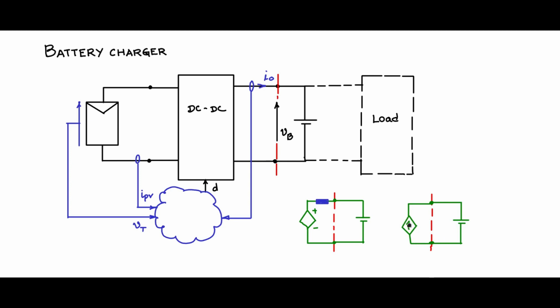It has the necessary impedance inbuilt within it, so that there will always be a current limit. Current sources and voltage sources can be connected in parallel. So we will follow this model, and that is what we will introduce into this control algorithm, which is a current controller. Let me draw and discuss the schematic for a buck converter based current controlled battery charger.